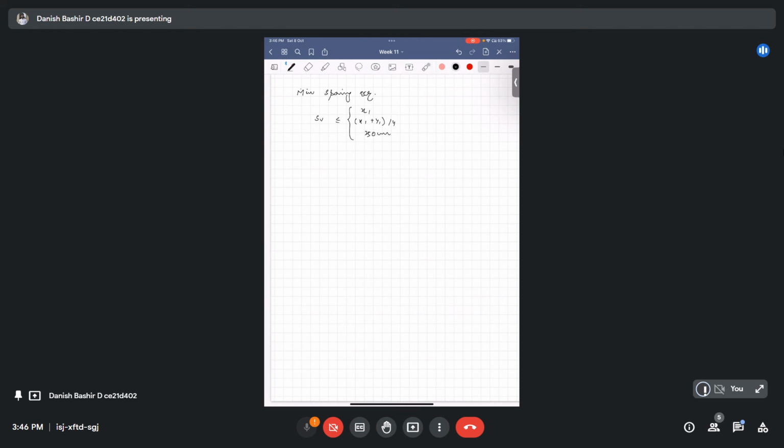Earlier b1 and d1 were from the centroids of the longitudinal reinforcement. Now x1 and y1 are the distances from the centroids of the stirrups in the breadth direction and the depth direction. So x1 will be 250, as we already got for b1, plus we have to add the diameter of the one bar that is 28, and half the diameter of the stirrup bar from both the sides, that is one diameter of the stirrup, 12. It is equal to 90 mm.